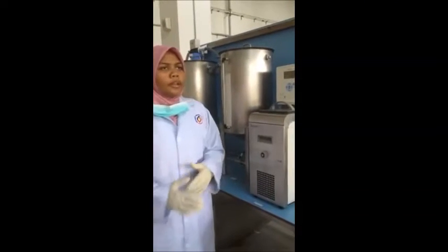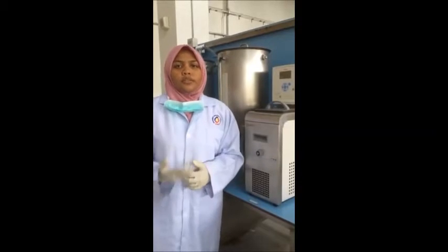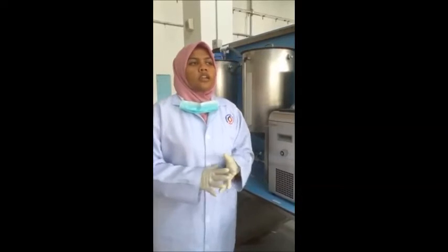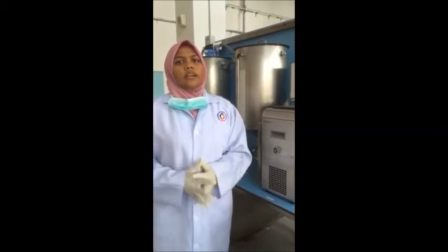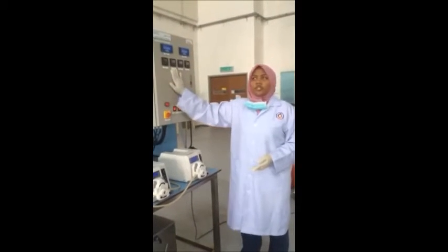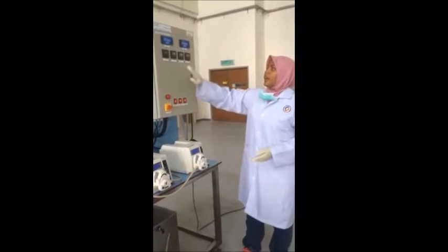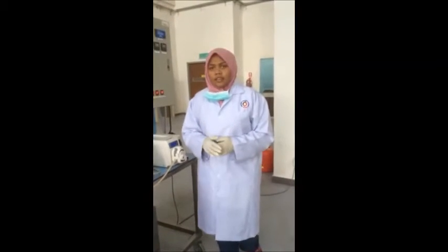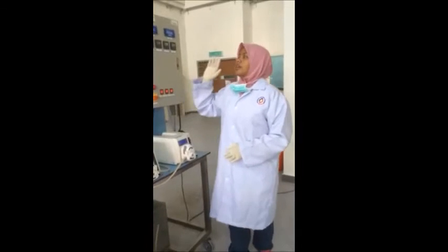That is the moment we start monitoring the values of Q1 and Q2, which are the inlet and outlet conductivity, and also the temperature of the reactor. It can all be seen in the control panel. What we are concerned with here is only TT2, which is the temperature of the reactor, and then the conductivity Q1 and Q2. The reading can only be taken if these three values do not change anymore over time. In other words, it is the moment the reaction has reached steady state, where the conductivity value and the temperature no longer change, and we take that reading.